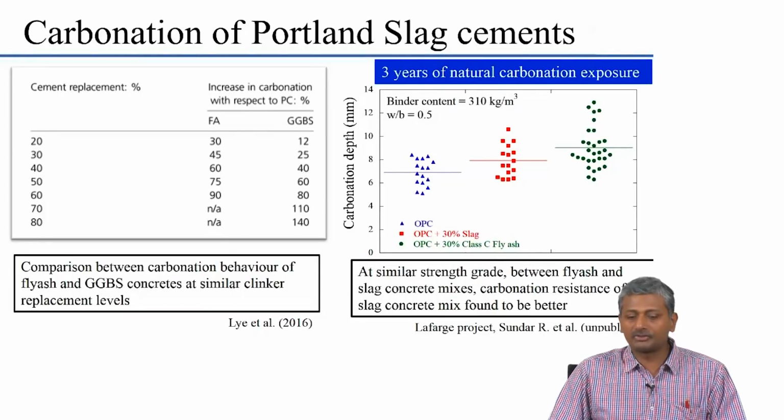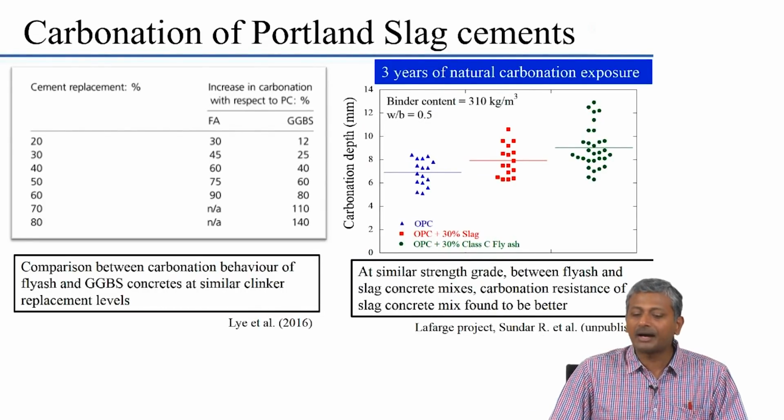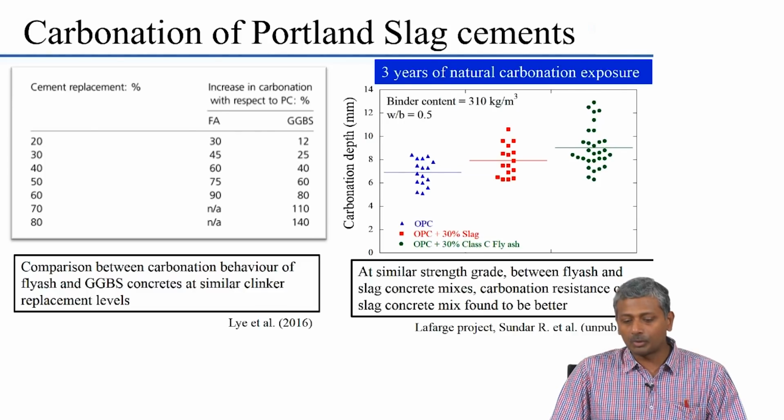We have discussed this briefly earlier, the fact that you have less lime, less calcium hydroxide in the system, may lead to conditions of carbonation happening in your system. So, again, carbonation of slag cements is generally higher than the carbonation of plain Portland cements.